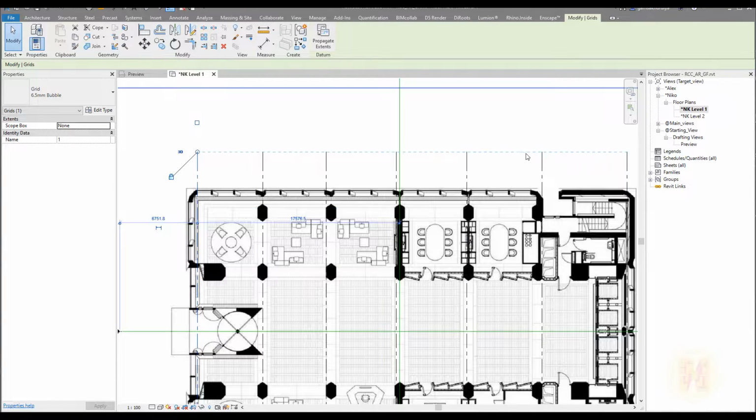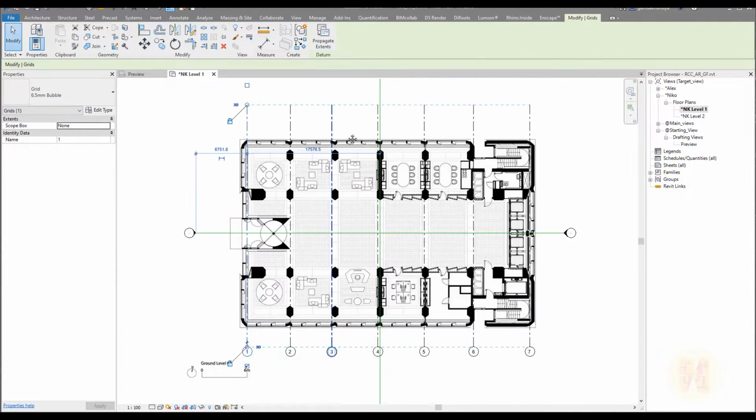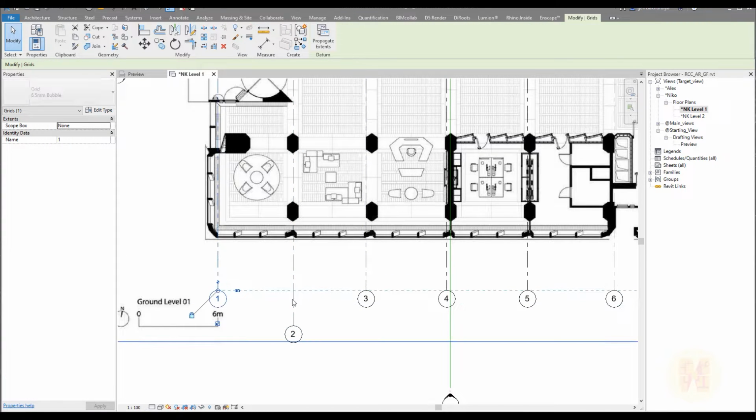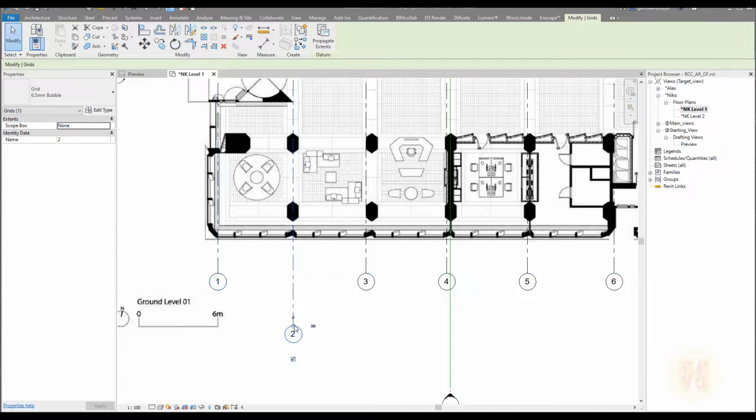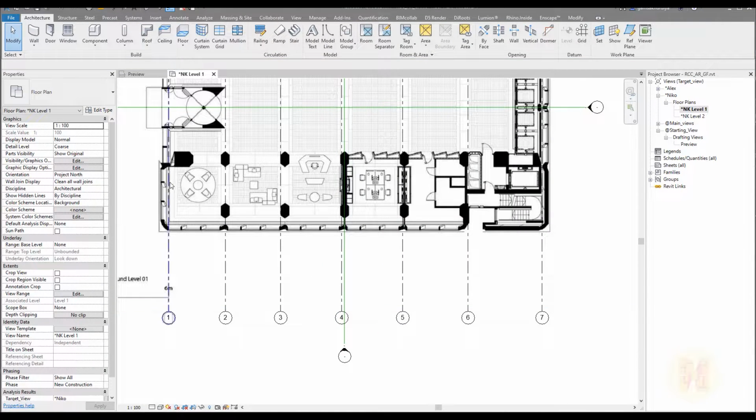The dash line shows you which lines will be moving with these two, and it's much faster working with the grids. The same thing here. It's exactly the same thing. Let me show you. Uncheck, and like that. As you can see, when I'm moving, only the lines without the lock move. And now you can drag and drop this one. You will get a dash line and click, and as you can see, now it's moving everything with the other line. Okay, this is a simple thing, you understand. Let me now try to prepare all my grids.